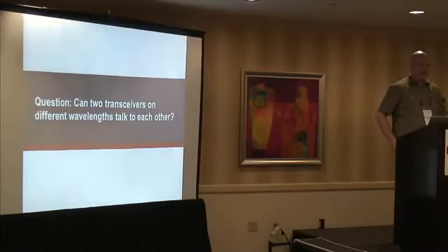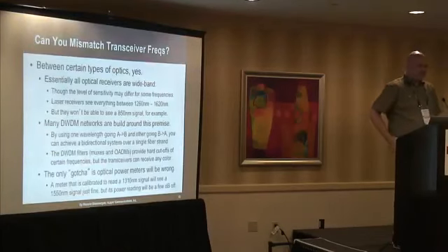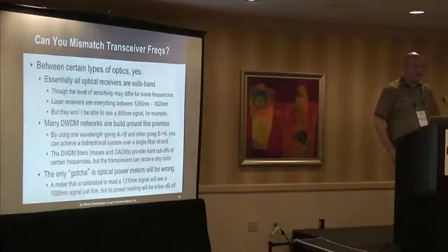Big question I get asked a lot. Can you make these two transmitters on different wavelengths talk to each other? More or less, yes. Basically what happens is all optical receivers are wideband. So if you're in the laser category, you're going to be able to decode anything between 1260 to 1620 nanometers. You're not going to be able to make an LED or an SX850 talk to an LR, but you're going to be able to make a 1310 and a 1550 talk to each other, absolutely.